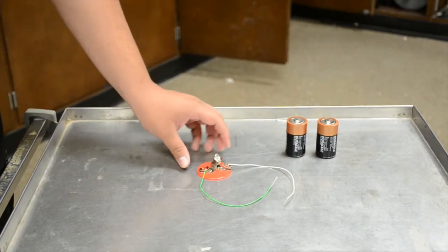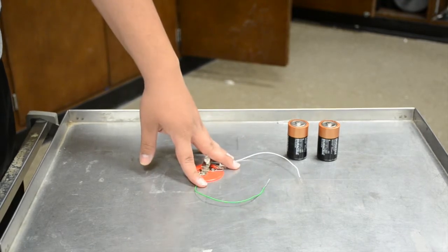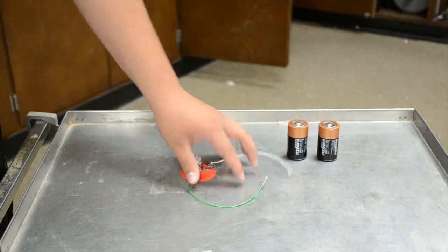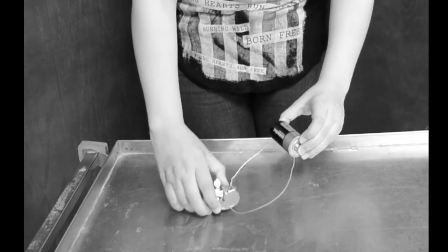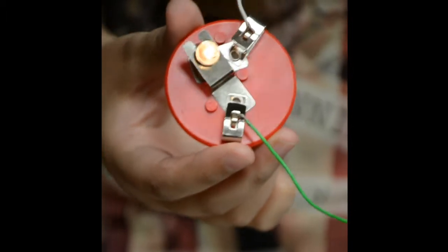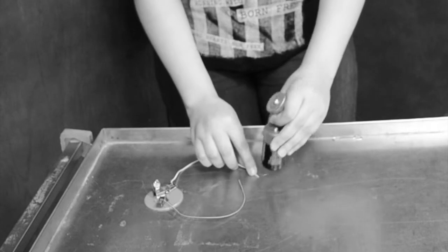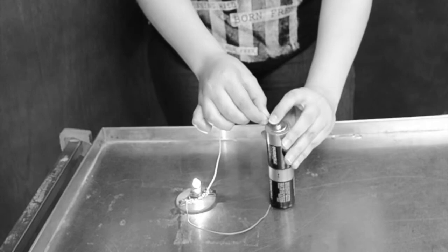We're using two conducting wires and two batteries with a bulb for a simple circuit experiment for potential difference. In the first experiment, we will use a 1.5 volt battery, 2 wires, and a light bulb. When we connect the wires to the ends of the battery, the bulb lights up and provides a dim light. In the second experiment, we will use two 1.5 volt batteries, making it 3 volts altogether, connecting the wires to the end of one battery and the end of the other. When connected, the bulb provides more light than in the first experiment.